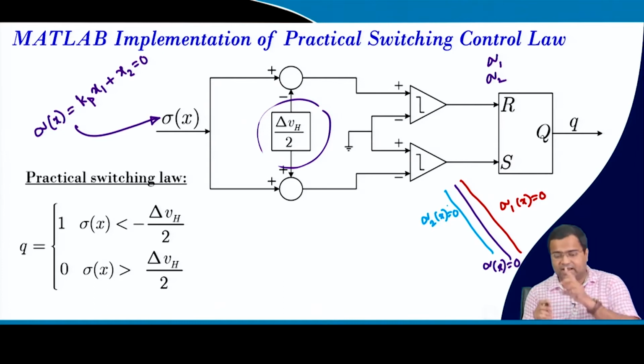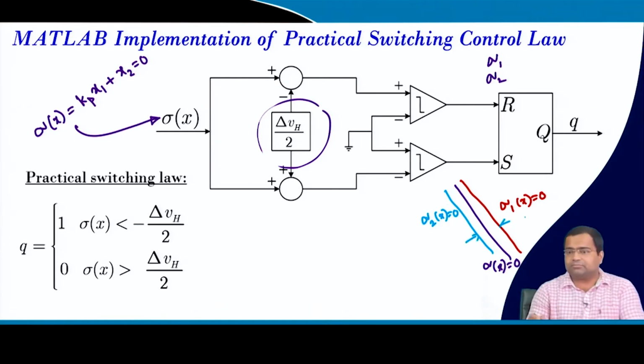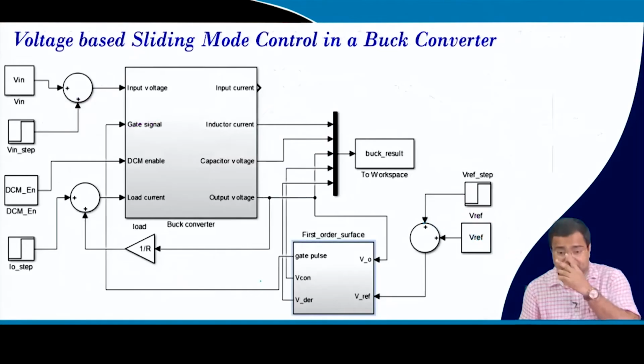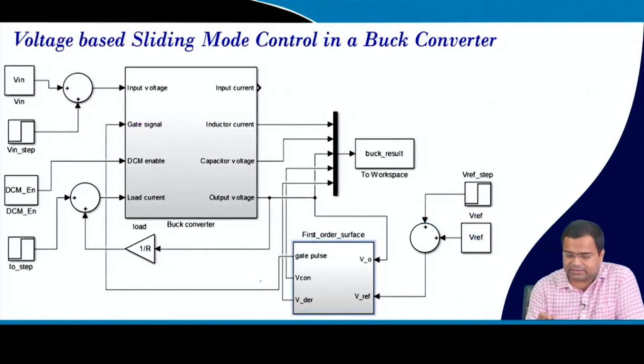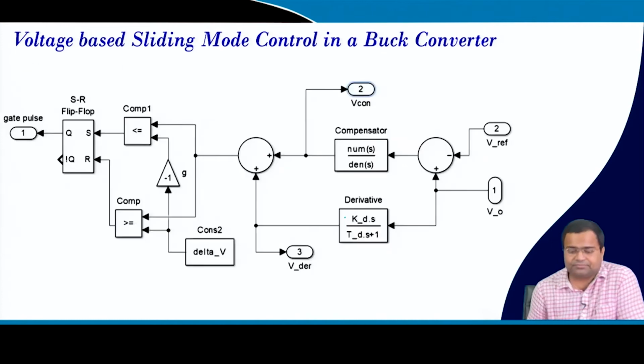So, this is a band, and we are defining this band in terms of voltage, because it is along the y axis, the voltage axis. So, we can implement this voltage based control, and that we have discussed in lecture number 46, where this is our band limited derivative.